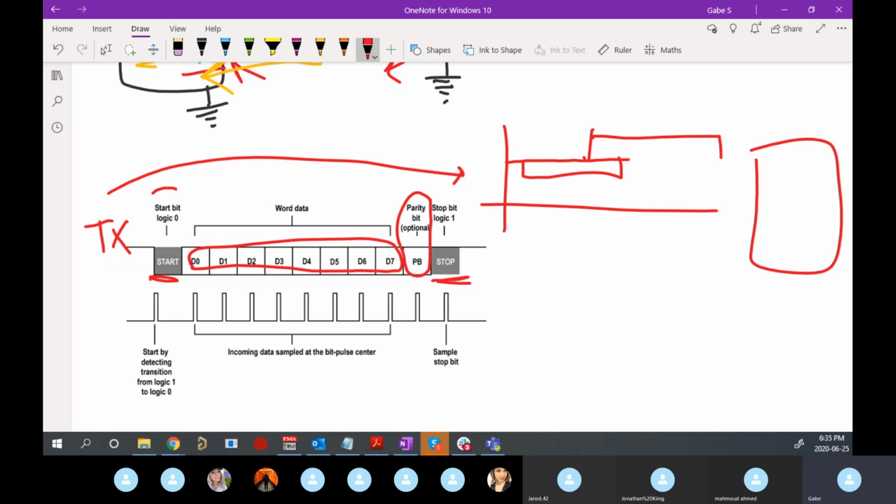So we have this start bit to make sure that the slave knows, okay, this is real data, and we can start with this bit. And then if we want, maybe we actually do want to send 8 ones in a row, and that's fine. But without this start bit, which is here, we're not going to know that that's real data and that we actually have communication.